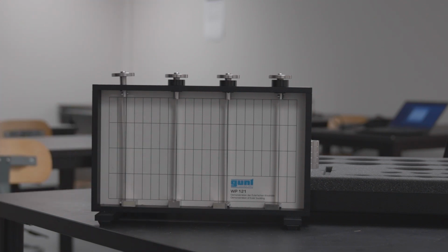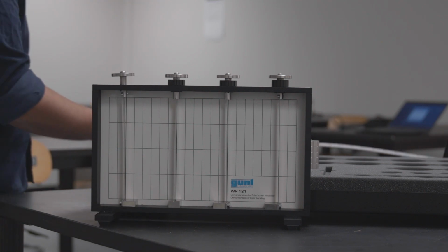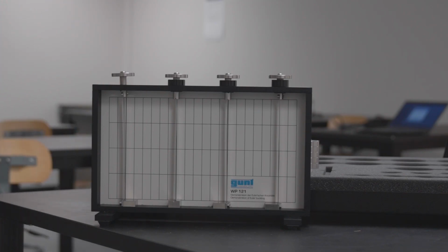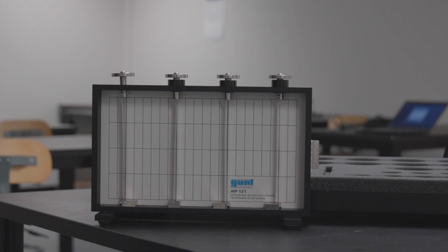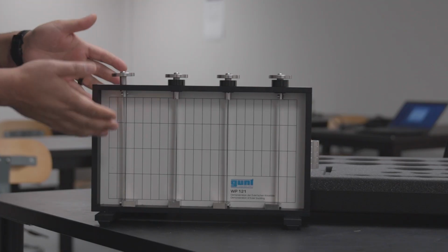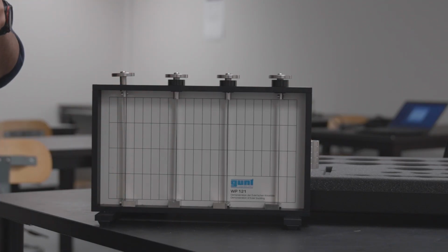With the length measurement and also the thickness and depth measurements, we are going to calculate the moment of inertia for the column. Then we are going to use the Euler buckling relationship that relates the load to the critical load of buckling based on the material of the column. We have the critical load of buckling, and we have done the measurement for the material. You can use the equation to calculate the modulus of elasticity, right?